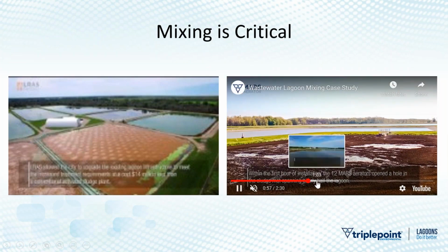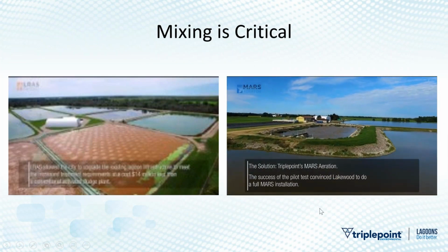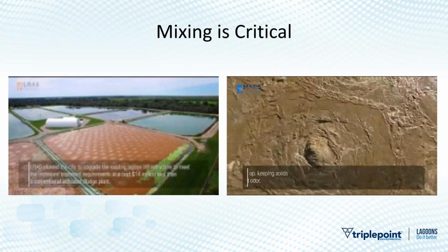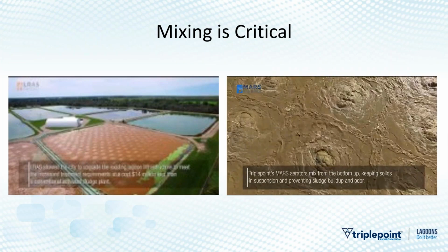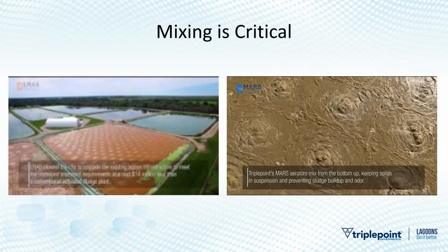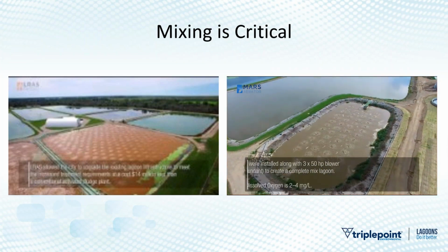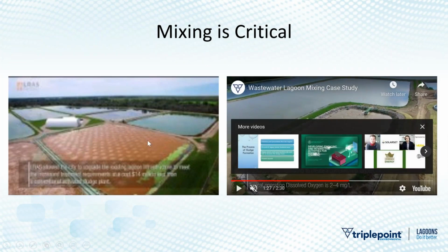We ended up doing a pilot with diffused aeration, and we ended up doubling the oxygen being transferred to the water. And you can see here, when we get enough air in, the sludge actually stays mixed in the water column. When it wasn't mixed and it wasn't aerobic enough, it actually floated and it created major odor issues. But you can mix quite a bit of solid. This is about 4 or 5% solids in this basin. And actually, you can look at that over here. That one's not playing ball, so I'll tell you a story about it instead of show it to you.